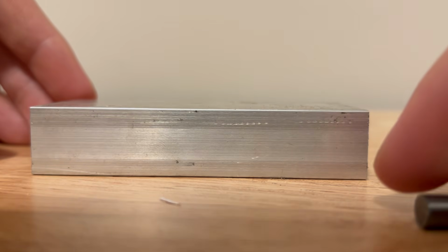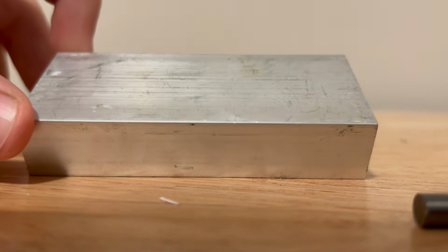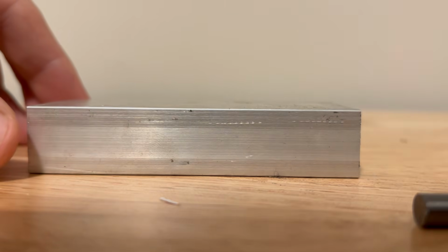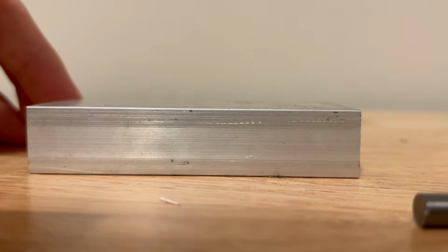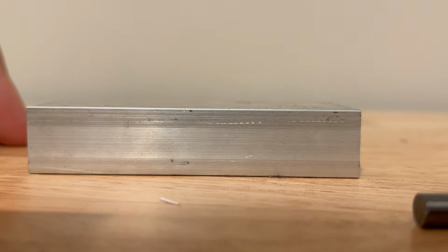And then you would want to make threads. So you'd use a tap, right? No. This is focused on the small hobby machines that are not going to have enough torque to rigid tap. If you don't know what rigid tapping is, we can go over that later, but tapping takes a lot of torque. You could do this by hand, or you could buy a thread mill. You have a CNC machine, so you should just use thread mills, and we're going to go over that.